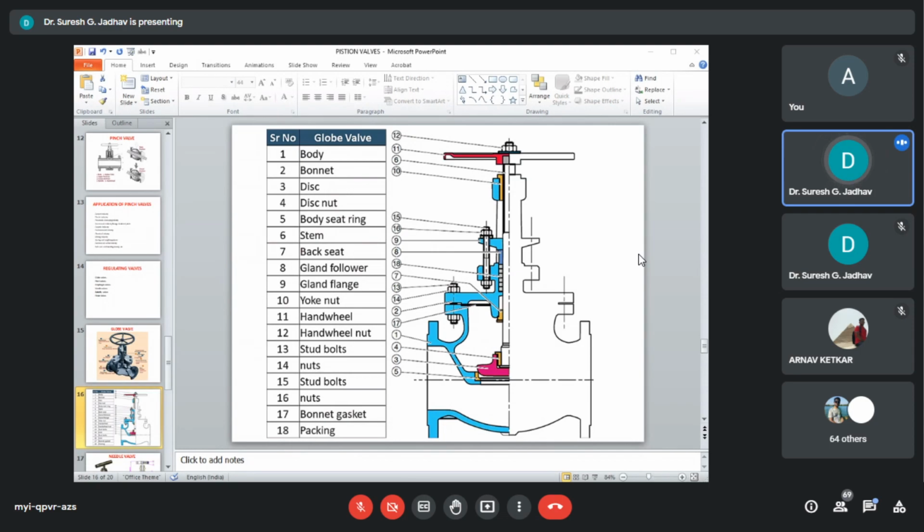First, flat face type discs are used when the valve is to be used for positive shut-off services. For such services, we can use that kind of valves. This can be provided with an elastomer ring or facing, which will ensure the same.